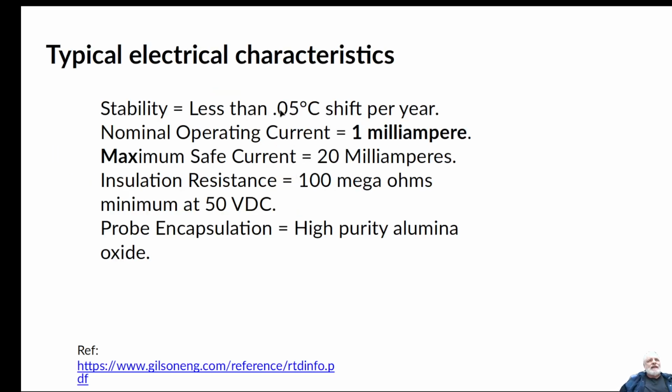Now, a couple of things about these RTDs, okay? They are very stable as long as you don't put too much current in them. So they're basically designed to work with 1 milliamp or less of current in them. But they can actually handle all the way up to 20 milliamps.